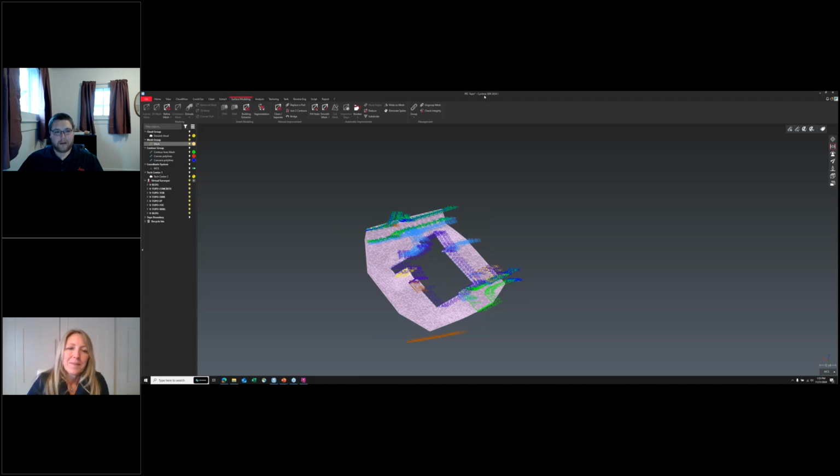Well, of course, the more you're able to capture and draw out, like as those break lines, like I've mentioned, the polylines, that's going to help you with your surface because you're capturing all the key elements in the surface. So then let the DTM tool get all the other stuff. So you don't need to try doing points on a grid in certain areas or drawing extra break lines. You just need to worry about the important ones.